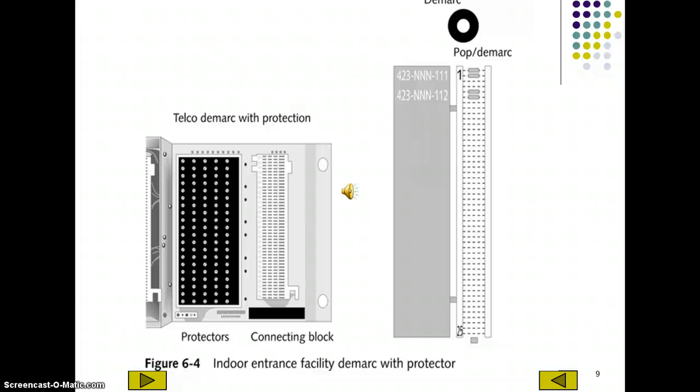Also note the oval shaped devices that go with the top of the terminations near the top of the 66 block on the right. Those I've run into in the field, typically they're red and they denote special circuits. The idea basically is to keep your hands off of it. It's a special communications circuit that if you put test equipment on, you could disrupt the data stream, thus causing a problem with the system. Typically they're high cap circuits, high capacity circuits.